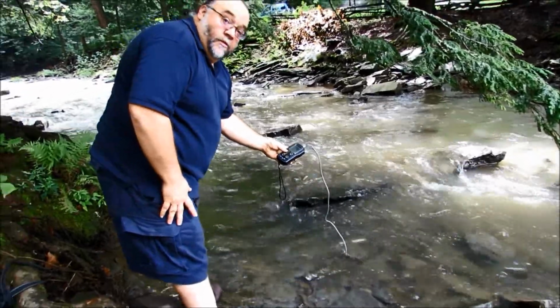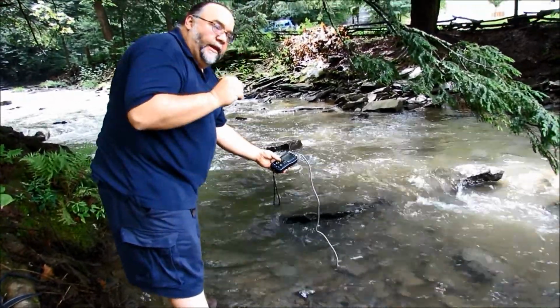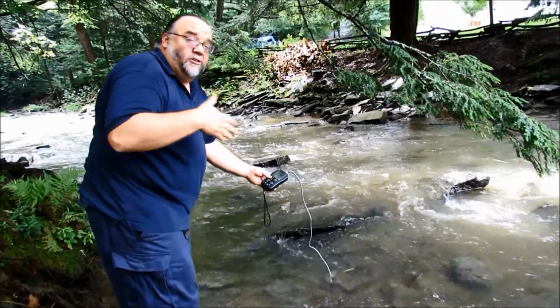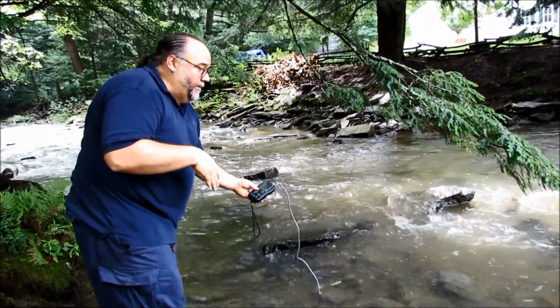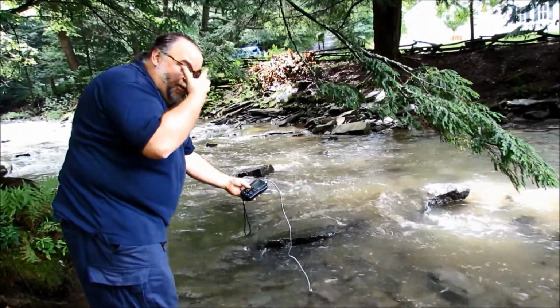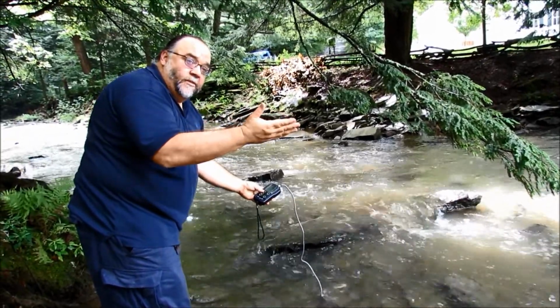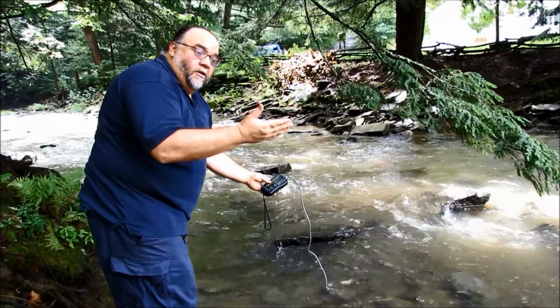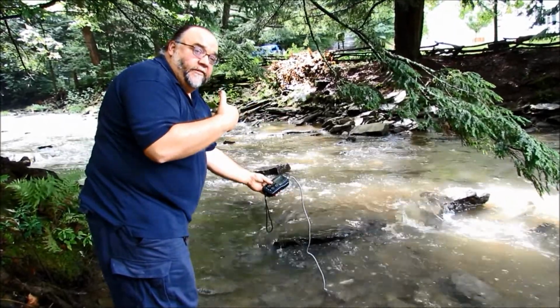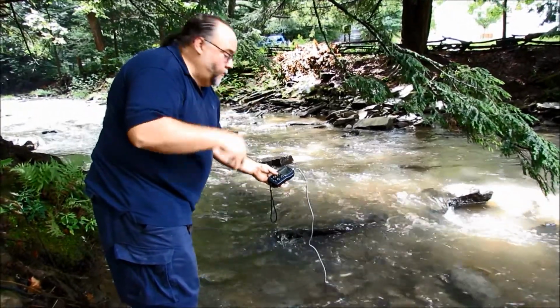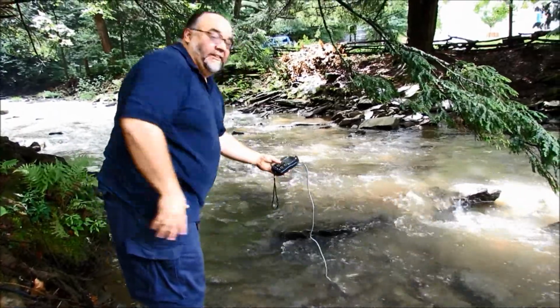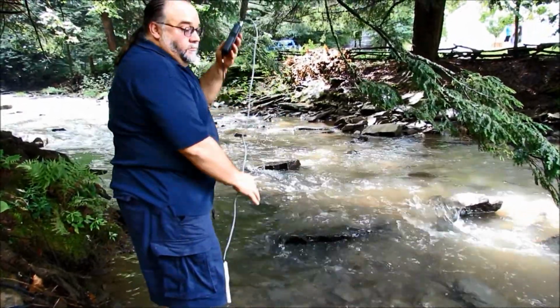What does a rainstorm do to conductivity? It can do two things. One, it can dilute. And the other thing too is the rainstorm could cause clay to move. Clay is a charged particle, and clays can increase the conductivity of water. So it can go either one. It can increase it or decrease it? Yes. Either one.